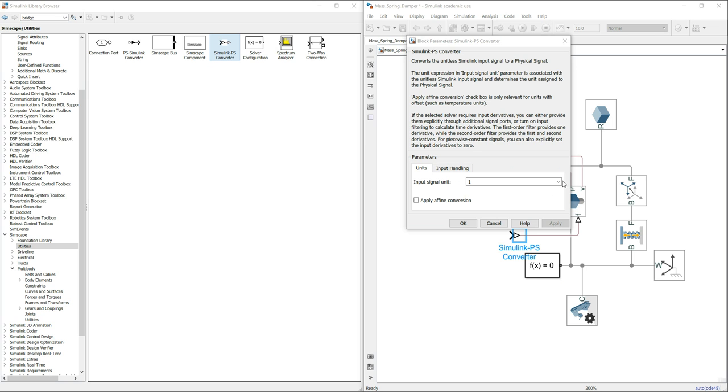On these input values here, I'm going to drop that, turn that to newtons, and on my inputs here it's asking for an input only. What I'm going to actually do is say don't calculate anything, these are zero derivatives. So basically what I'm saying to the system is I don't want you to take anything else from this input. All I want you to give it is a direct force under my commands. So I click zero derivatives, piecewise constant, and we're going to say input, click apply.